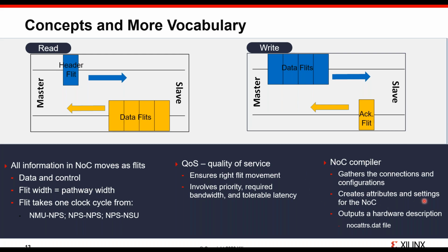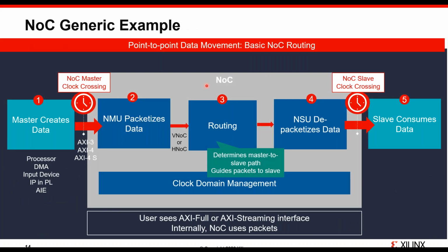And that's what you're describing, or letting the compiler describe to you at that point, is how to go off and use these things. So again, it outputs a hardware description file that would be included, as it's no longer a bitstream anymore. It's much more than that. So part of that is getting this NoC attributes.dat file. There is a NoC in every single ACAP, so there will be a DAT file associated to every single ACAP that you create going forward.